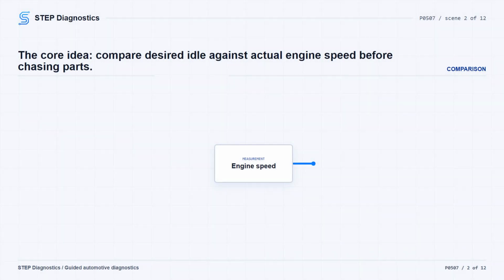Possible areas can include fueling concerns, fuel contamination in the oil, aftermarket fuel system equipment, or operating conditions that make the idle check invalid. Before you get deep into it, start with the basic system checks and follow a structured diagnostic approach so you do not jump straight to parts.